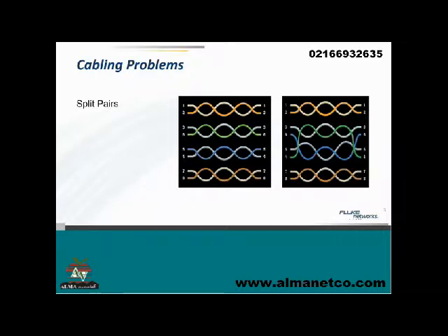How would I test a cabling job done by someone else when the cables are Cat 5e, but cable and patch panels are Cat 6? I presume it would only pass with the weaker link. Okay, so here's the deal on that. The standards say that if I build a link that is designed to pass, say, Cat 6, we'll use that as an example, I have to use Cat 6 components. Now, I could build a link that used some Cat 6 and some Cat 5 components.